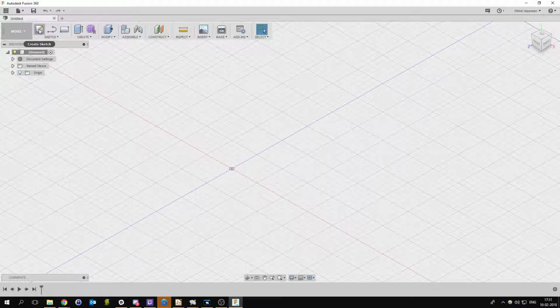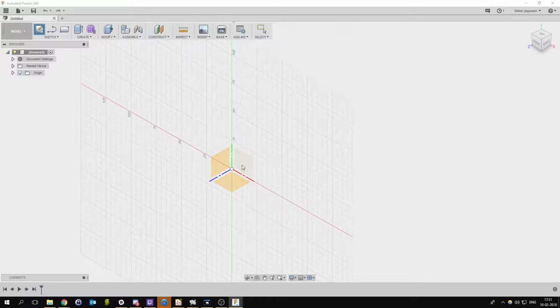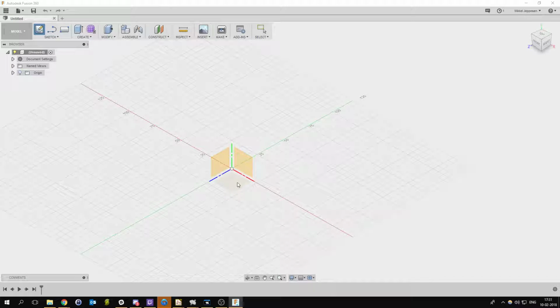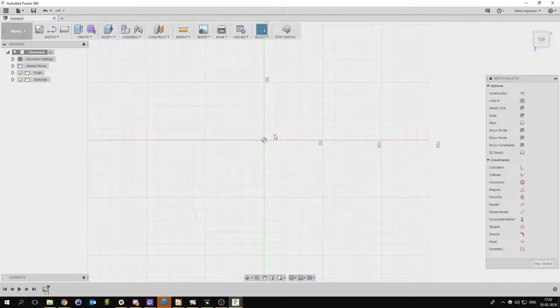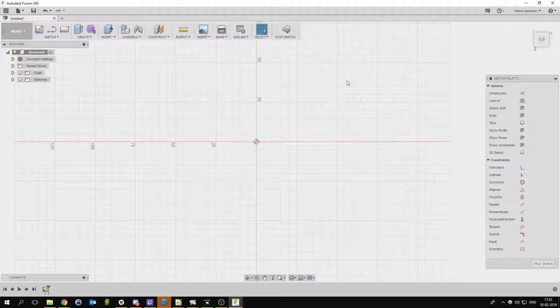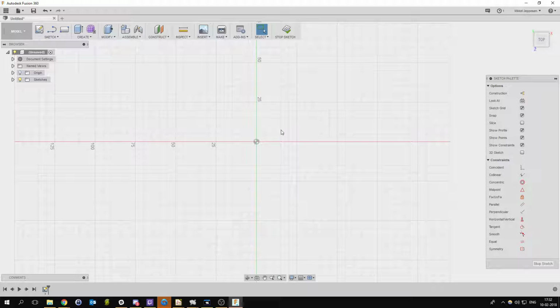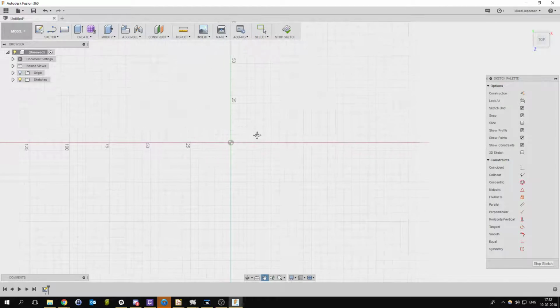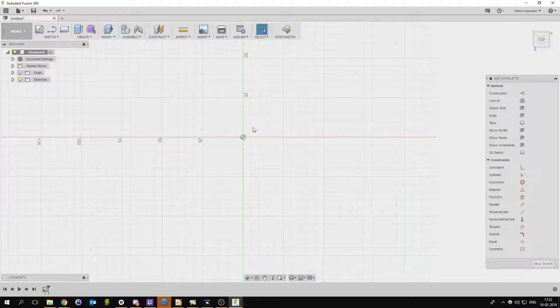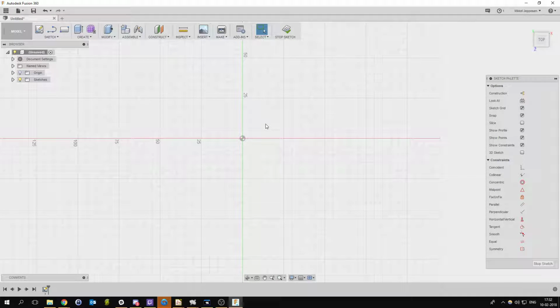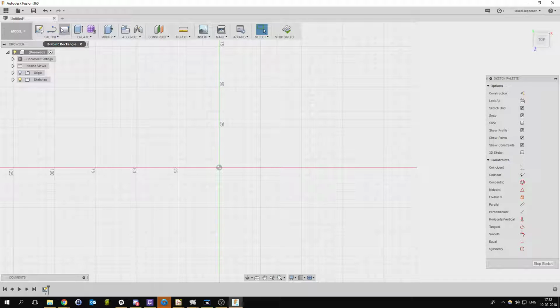So the first thing you want to do is create a sketch, and then you select the plane to do it on. Normally I do it here in what I use, called top plane. So you start a sketch here. I don't really know the shortcuts, yeah, it's called top here too. Okay, so middle mouse button to move around; maybe you cannot right click in a sketch. Anyways, so then in the sketch, let's say, what should we make?